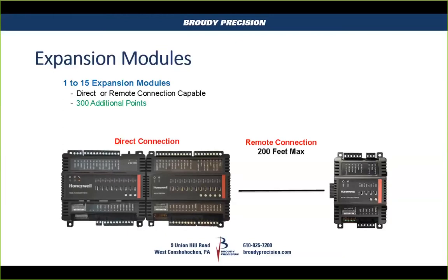So Frank, just to mention, HOAs on every output on the expansion modules as well. Yeah, all outputs, whether it's the controller or the expansion modules, you get the overrides, and also that they are supervised. They do provide feedback. But you have the limitation where with a software override, there's no permanent duration. Right. And obviously with a switch, it's permanent until somebody puts it back to auto.